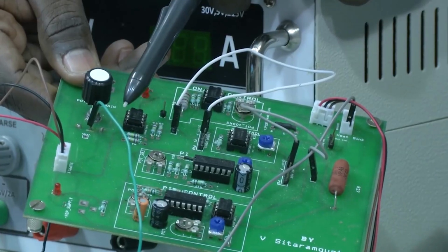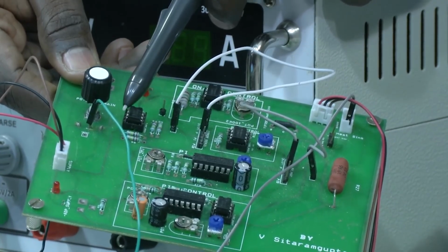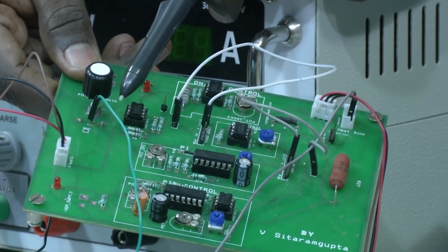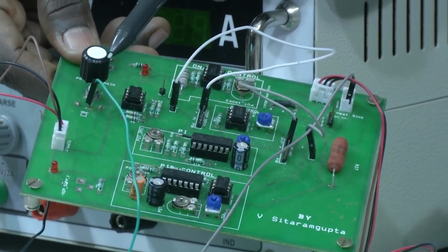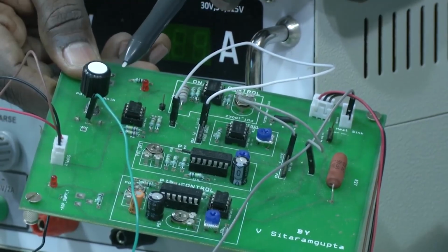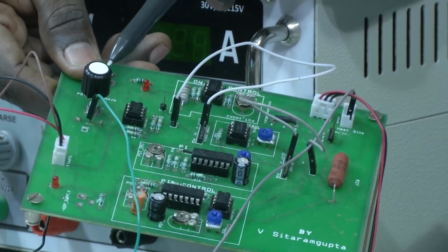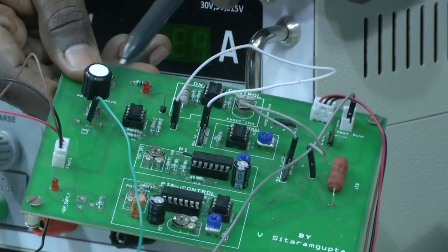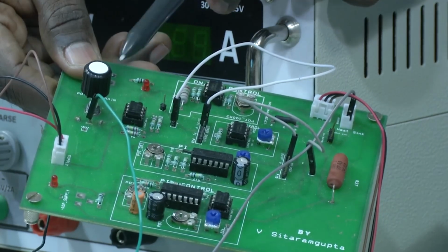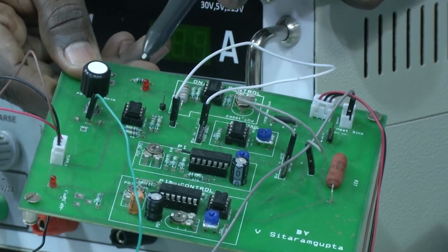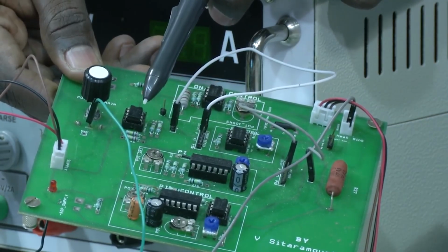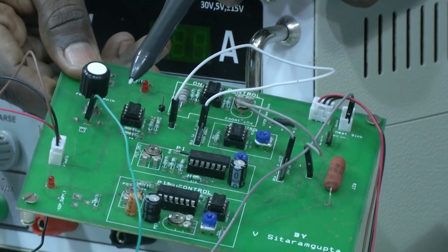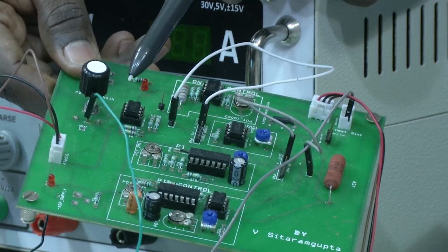What we have used is the TL082, which has 2 op amps. One op amp is a simple voltage follower, in order not to have impedance mismatch between the output of the pot and the differential amplifier. The output of the pot is connected to the voltage follower, and the output of the voltage follower is connected to the differential amplifier, whereas the other input to the error detector is from the sensor.